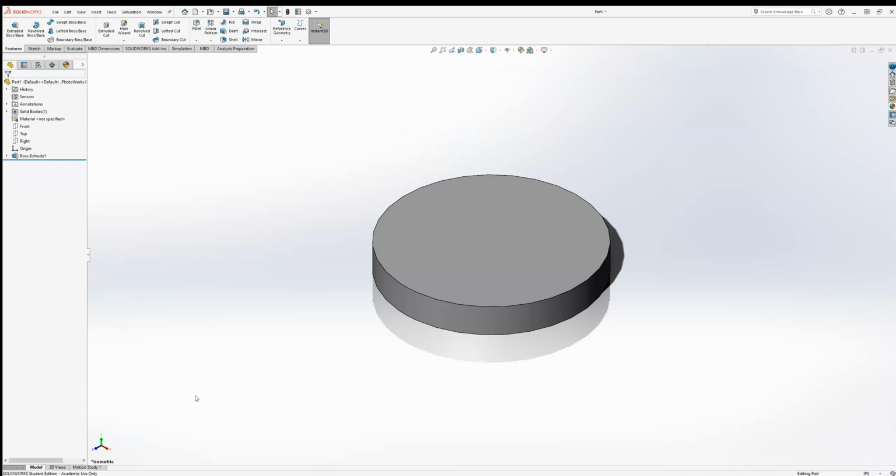And this time, I'm going to do a slightly different way. Now that I've got geometry in place and a flat planar surface right here, I'm going to start my sketch on this face instead of on one of these default datum planes. And so one way to do that, which is a little bit quicker, is just left click on the face. You can see this little quick access box pop up, and I can click this icon right here to create a new sketch on that face. So I'll click it. And now it's a little subtle, but I'm now in a sketching environment again.